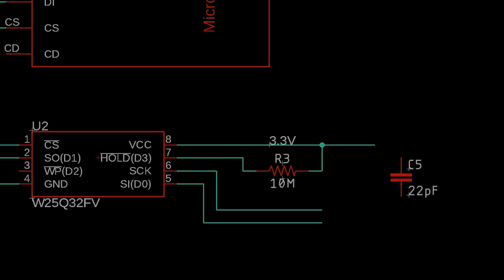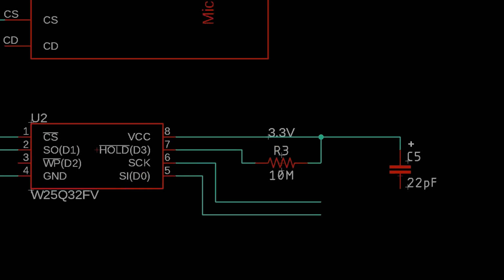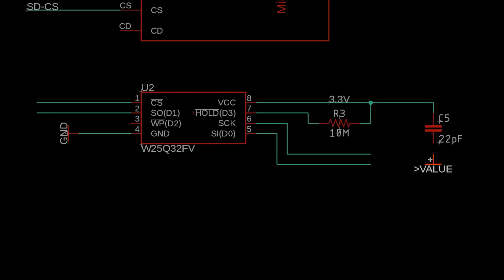Now there's one more thing that we want to add here, which is a small capacitor. This is another one of those components that usually would exist on a breakout board, but because we're not using one, we have to sort of do it ourselves. So I'm going to put a capacitor here, connected from 3.3 volts on this device to ground. This is just another little filtering capacitor, so any spikes or shocks in the voltage for this little component are going to be absorbed by this capacitor.